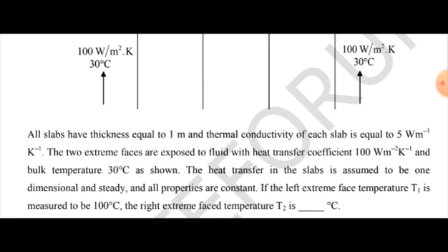If the left side surface temperature is 100, similarly it should be the same on the right side also. The students will determine the answer by that logic itself, but it is absolutely wrong in this question. In the first half of the question I have said that heat is generated non-uniformly, then how will it be equal? That is the key word in this question.